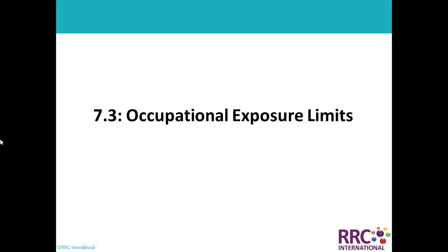Even the IDLH of H2S, immediately dangerous to life or health, is 100 ppm. That means after 100 ppm, you already cross the line of fire. So yes, Mr. Hamad, absolutely right. Below 10 ppm, but the ideal environment is 0 ppm.